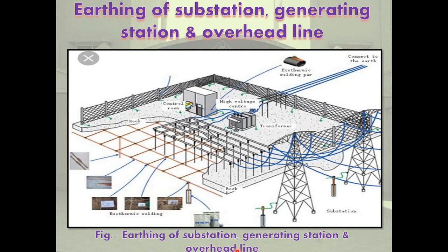And next is typical station earthing systems and the earth electrode spike. The station earthing system has the following components. First is a horizontal underground earthing mesh of steel rods. Second is risers, and third is earthing conductors. The earthing mesh is formed by welding horizontal steel rods placed in trenches at a depth of about 1 meter.